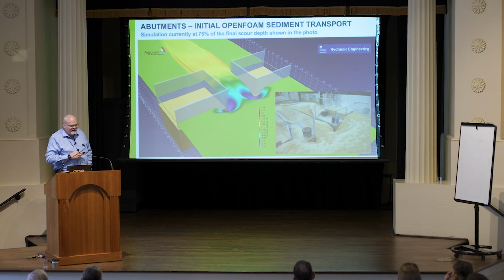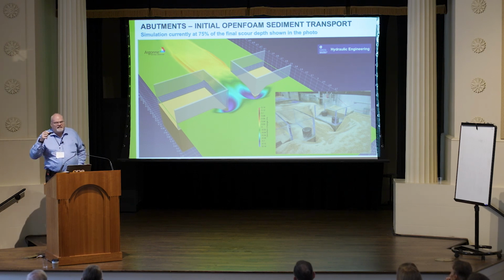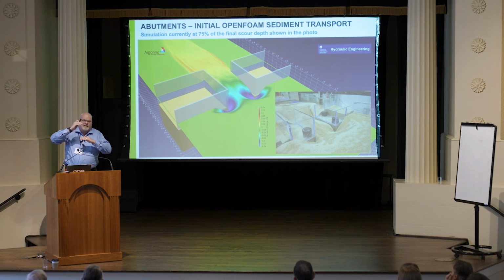One of the things that helps with the deposition is that we have a friction model of the dispersed sand with a riverbed, and we have no idea what to properly set. We also have a layer of sand floating over the riverbed, and this might be actually interesting. We're not talking about multiple cells worth of sand within our simulation. We're talking about small fractions within the first layer.